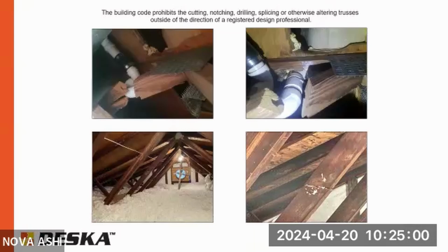So from an inspection perspective, if you're in an attic and there's a truss that's been cut and sistered, you would expect to see there in the attic, posted somewhere, an engineer's sign-off stamp like this was actually done by a professional engineer. In a perfect world, yes. Yeah, exactly.